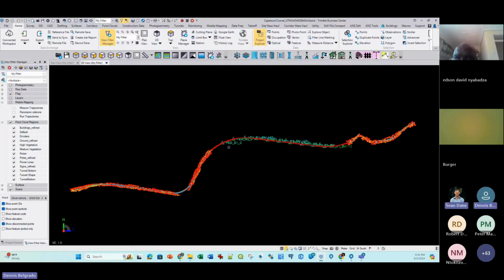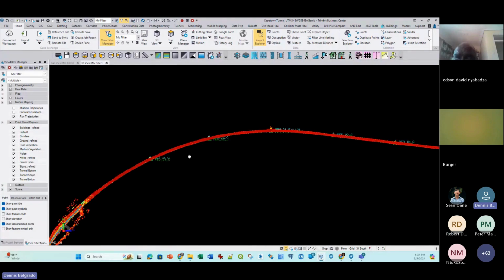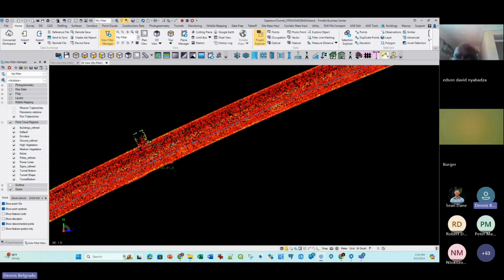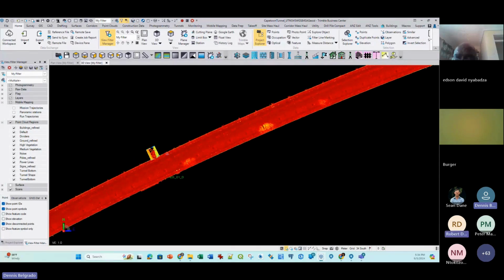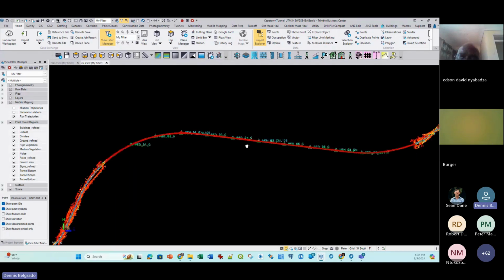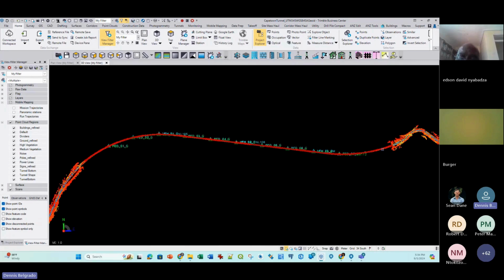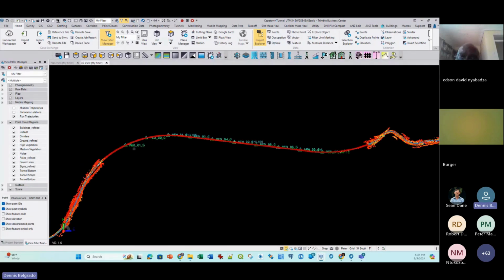Yeah, the controls. Yes, absolutely. So those guys actually created controls. So this is now the tunnel. They've created controls either side of the tunnel, so you have one from this side here at the bottom and another one here on the top. The distance of this control is around 320 or 325 interval from one point to the next, and so on and so forth. So you can see this is around 4 kilometers. We have around 12 pairs of controls.